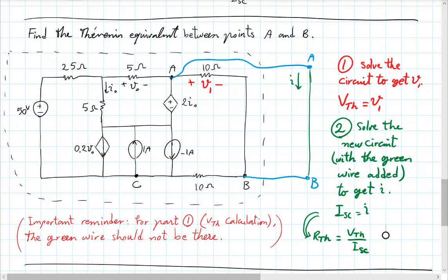And then, having those two voltage drops, you can calculate the voltage drop between A and C, paying special attention to the directions, polarities. Okay? That would have been my VThevenin for the equivalent circuit between points A and C. And that would have been a very different Thevenin voltage. The Thevenin equivalent would have been different.